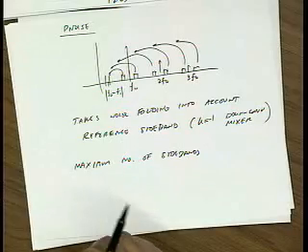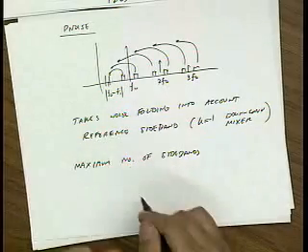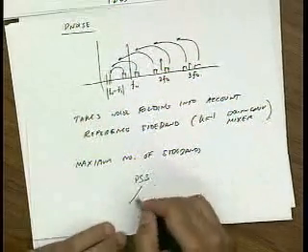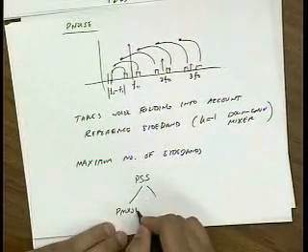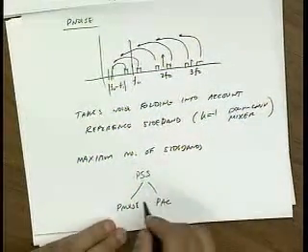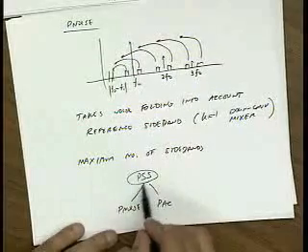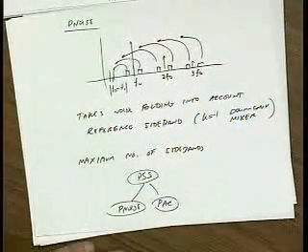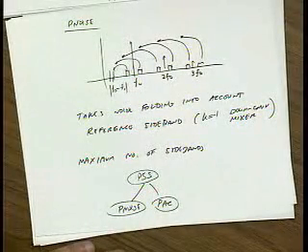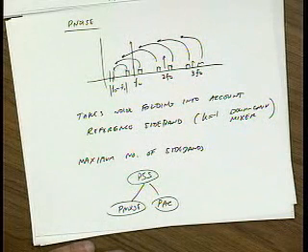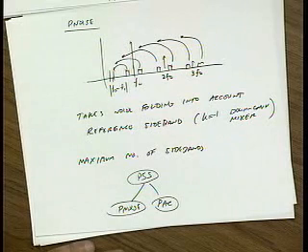Okay, questions about PAC, P-noise? So just like PAC, you first have to run your PSS simulation before you can run your P-noise simulation. Yes? Do you also need to specify the bandwidth over which noise is integrated? Because bands all have B's in the equation.